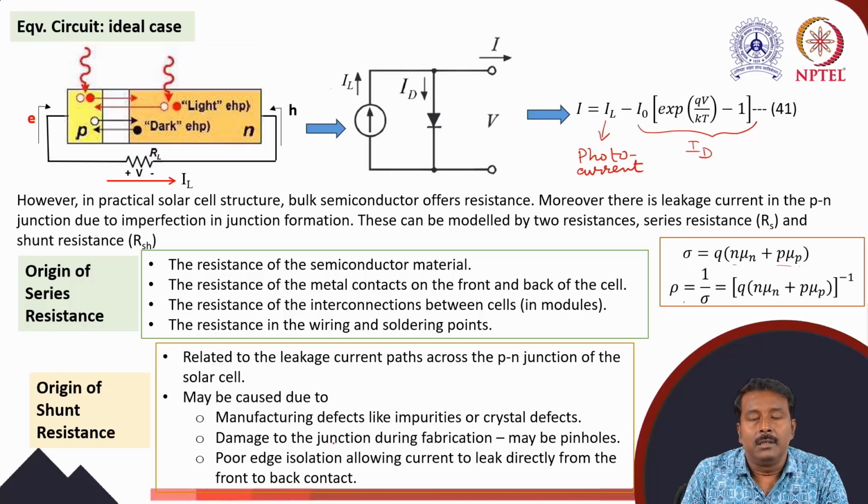So during that period, the surface of a P region may be damaged. That means basically in the junction between P and N, there will be some damage, and defects obviously are the result of this damage, and due to these defects also there is some leakage current.